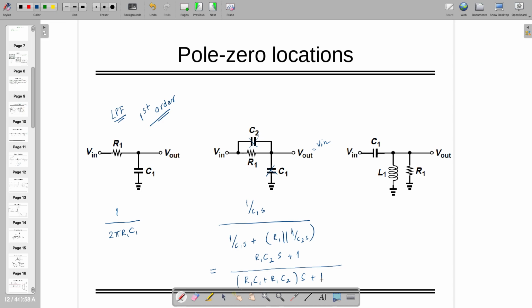So it's not second order, by the way, right? But here there is a thing that this capacitor is connected between input and output. You can see it's connected between input and output. In that case, it creates a zero. So that is what created here, right?